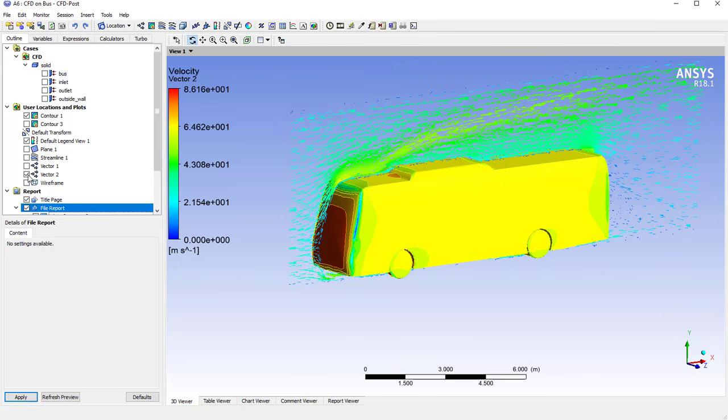I had just extracted the same thing, and then initialized the model with respect to the input and took the frontal area as a reference, and then finally reviewed the results and computed the results like CD, CL values and other things, and finally previewed the results by using the report options. Okay, so contours, streamlines and even the velocity plots and pressure plots and all.